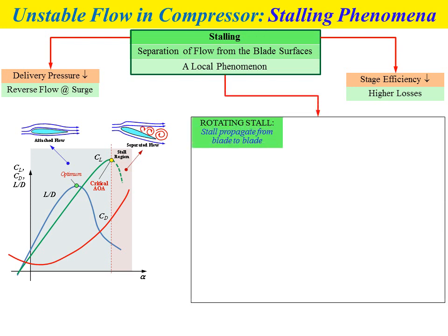Okay, so this stalling phenomena has a close relation to the rotating stall. Actually, in the actual compressor, the stalling phenomena will occur in the form of rotating stall, where the stall phenomena propagate from blade to blade.